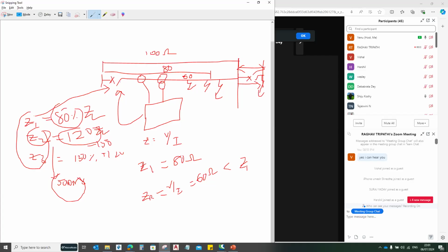We use this approach to avoid interrupting power to the other users, and as these are interconnected systems, you can't trip the circuit breaker unnecessarily if the fault is not within your protected line. That is why we call this a time graded protection philosophy, the distance protection.